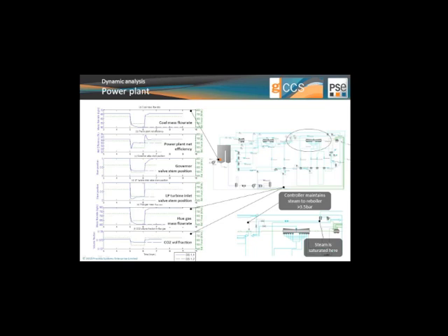And again, what you can observe is that the steady state requirement sees more steam flowing into the LP turbine than it actually does during the first change. And again, it takes roughly 30 to 40 minutes to settle to that steam value. So this actually leads us to think that more steam is being diverted to the capture plant in this initial 30 minutes following the disturbance.